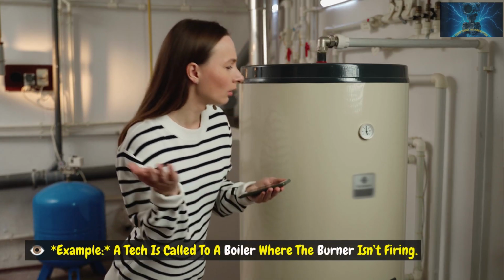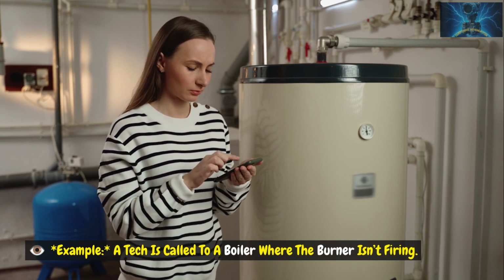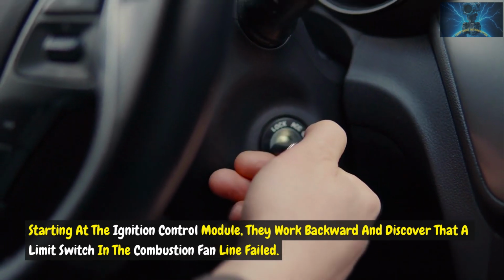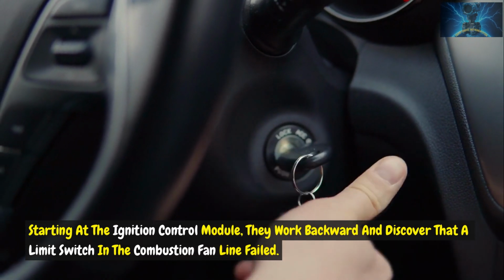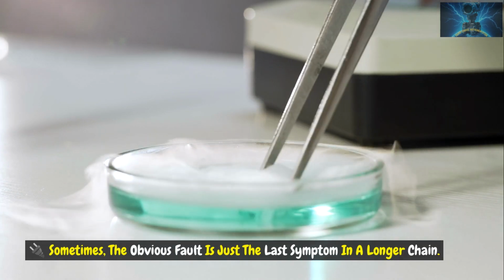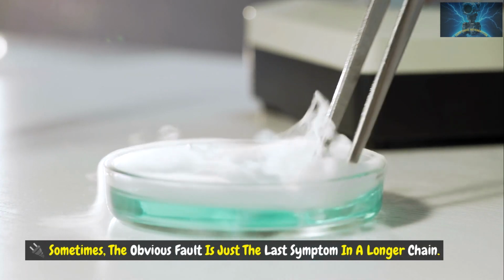Example: a tech is called to a boiler where the burner isn't firing. Starting at the ignition control module, they work backward and discover that a limit switch in the combustion fan line failed. No airflow, no burner. Sometimes, the obvious fault is just the last symptom in a longer chain.